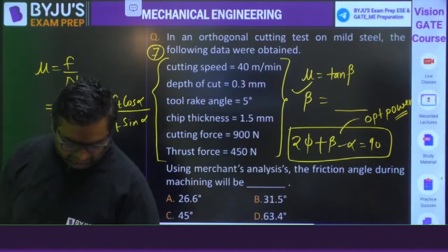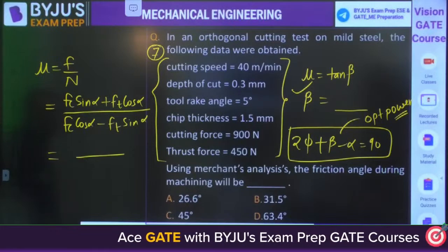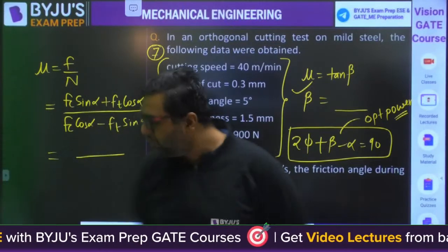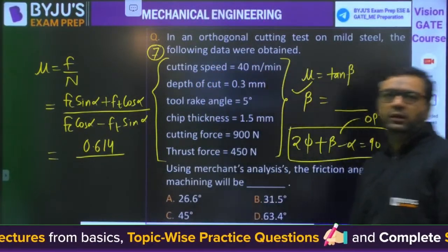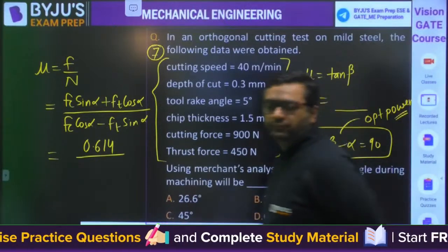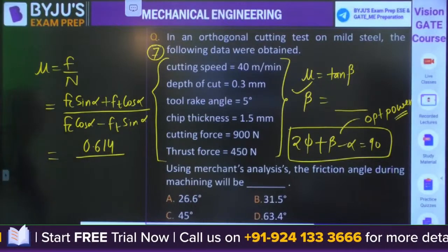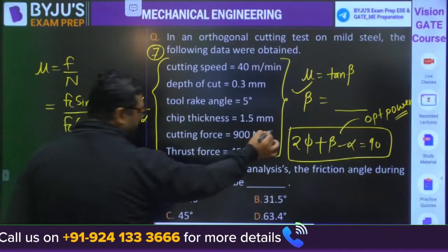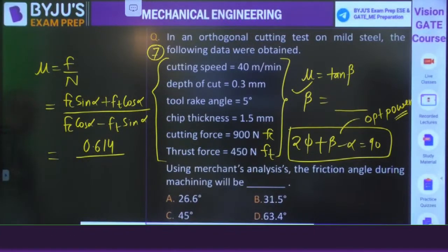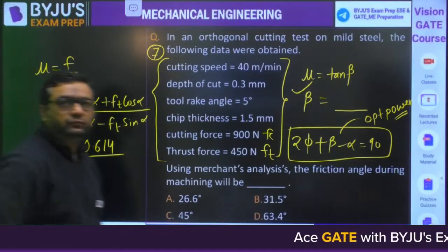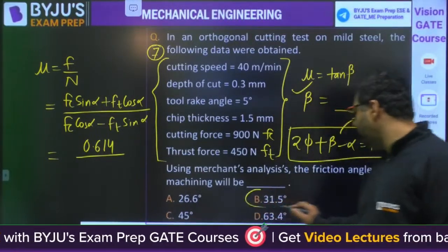Okay, Tushar is saying D is the answer. Once again recheck it. What value of mu are you getting? Are you getting mu to be 0.614? They have given you the cutting force Fc. Ft is there. Yes, Mani's answer is correct. The answer will be 31.5 degrees.